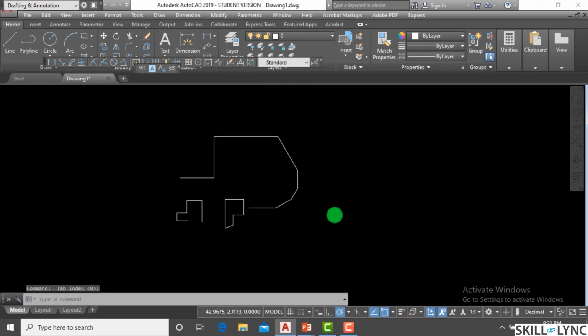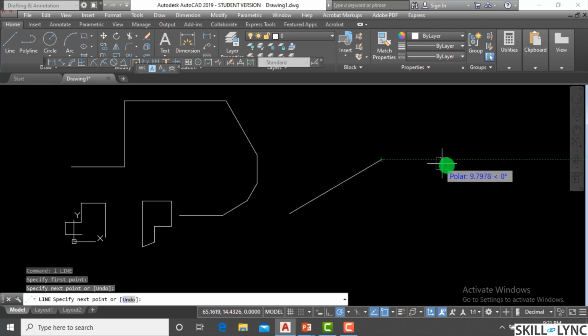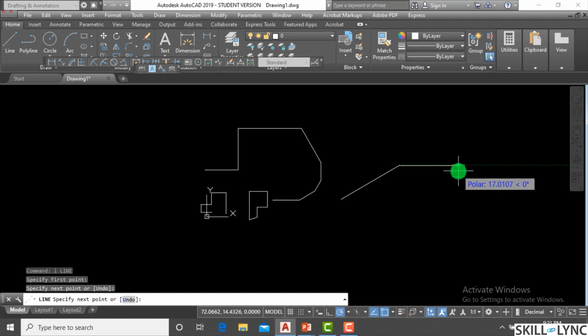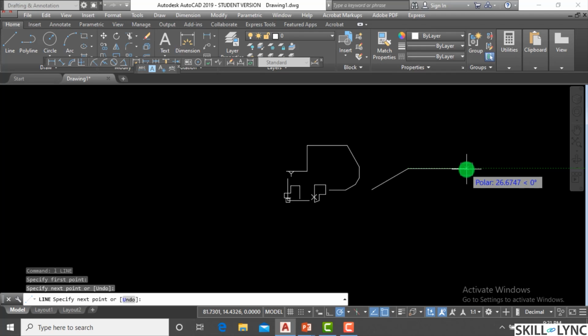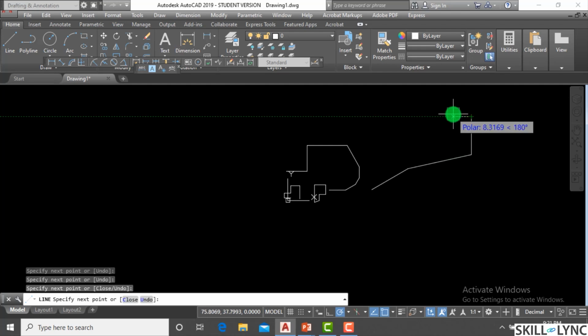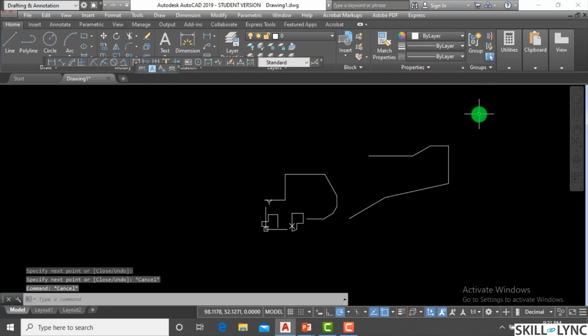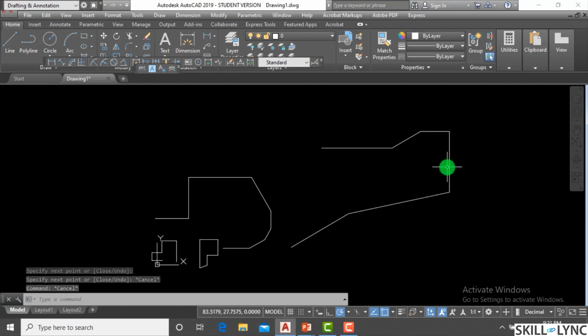So what is happening is, absolute means, once you're tracking, now just observe, you have this 0 degree, and then you have the track for the additional angles 12 and 15 and 30 degree. So again you have the 0. Absolute means the absolute base angle is the x-axis, so all the angles are measured from the base axis. So it is again 12 degree, and then the additional angles are there, the incremental. It will now go according to the incremental angle. So the meaning of additional angle is not the increment, but at 12 degree from the 0 base.